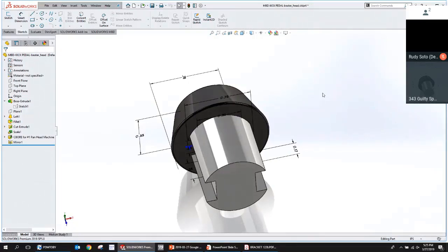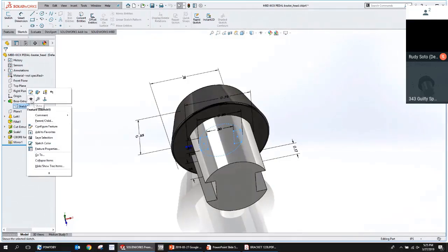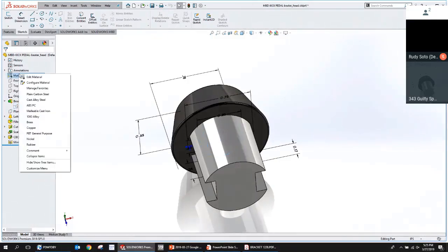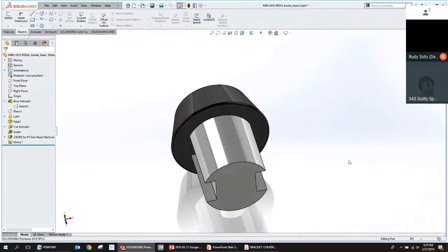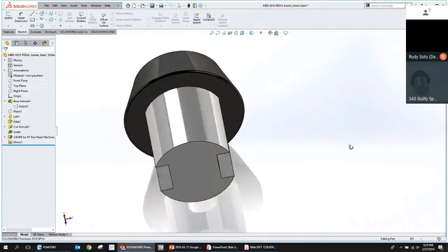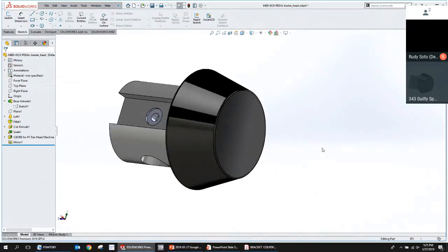Because when you're defining these dimensions, you're defining them typically to sketch geometry, but when you define the DimExpert information, you're defining it to faces. And that's what's carried through into the downstream applications. So you do have some options, but for the most part, you're going to be using what's in the DimExpert for the MBD and PMI information. So the whole DimExpert process is rather redundant to the model process. Nice.